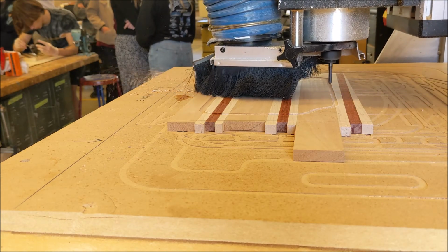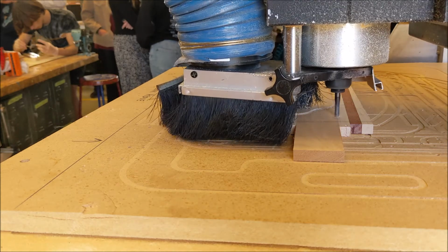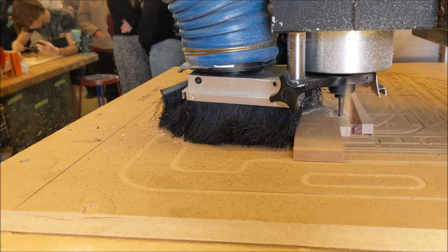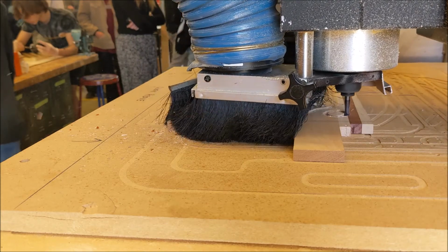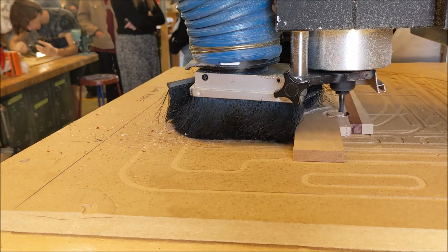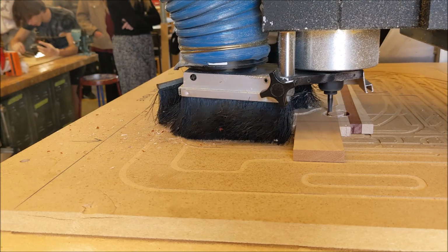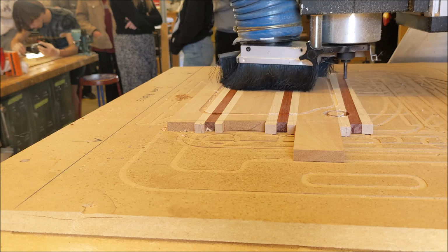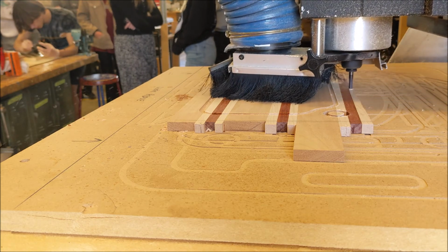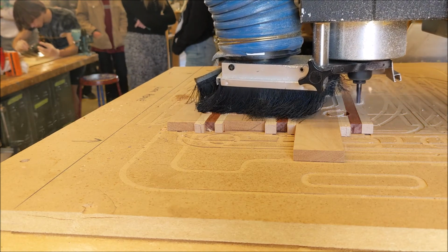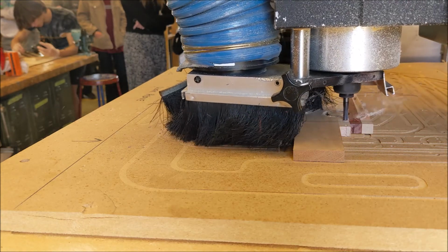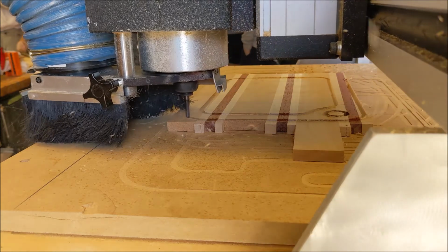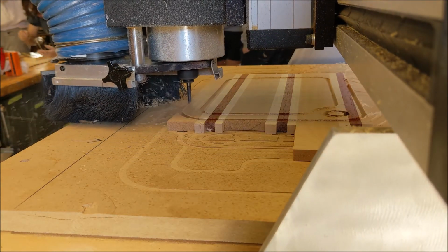But as it comes over to the hole it's cutting out here, it's going to travel counterclockwise with left-hand compensation and cut that hole out in 2 passes. When it's finished cutting it out, I actually have it set to do some finishing passes to clean up the cuts a little bit. I'm going out to cut out the part now. It is also left-hand compensation. However, it is traveling clockwise around the part, and that cutter is also spinning clockwise, so that is a climb cut versus a conventional cut.